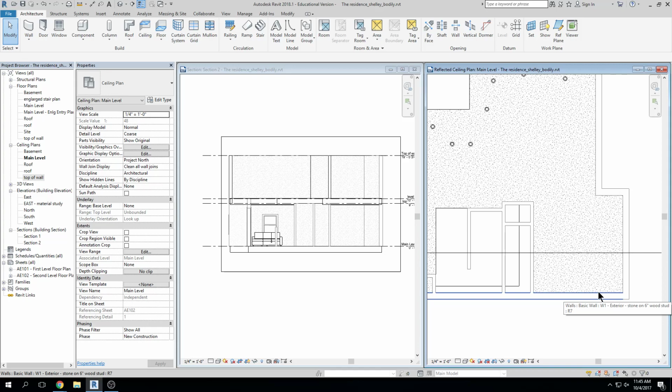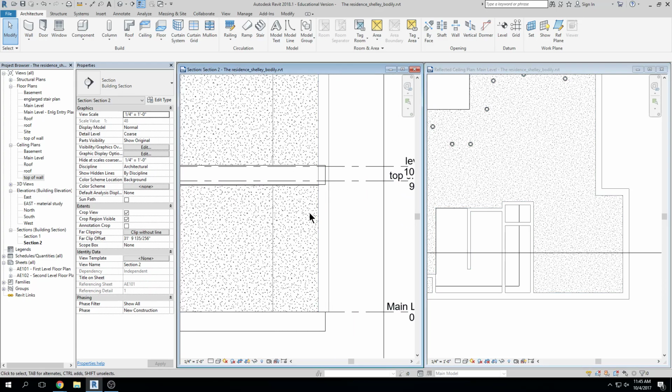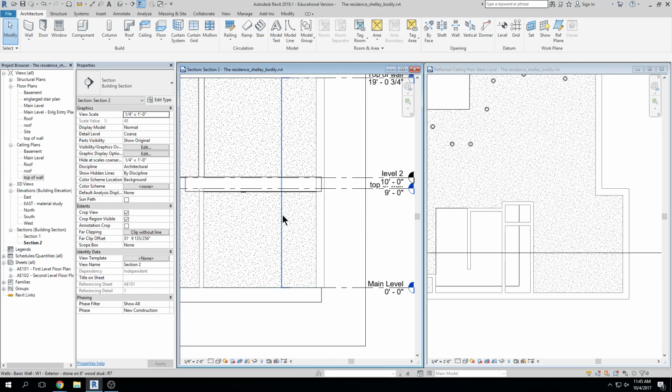I want it to start at, we have 9-foot ceilings, let's drop a soffit a foot down. So I want another little ceiling piece to be a foot down right here. The studs would attach to the walls back here, we'd have one coming down and going across, and there'd be framing all the way down to establish a soffit right here. Does everybody know what the term soffit means?